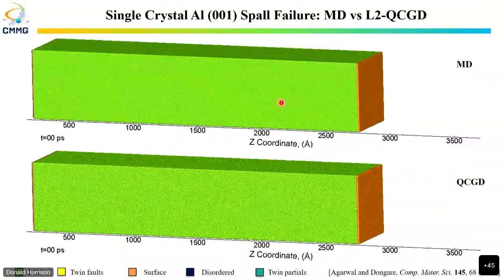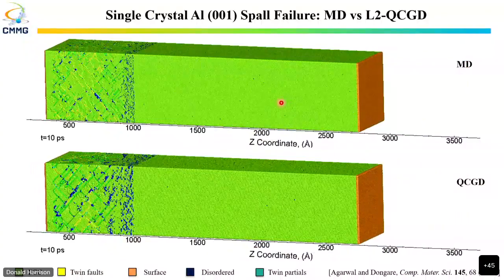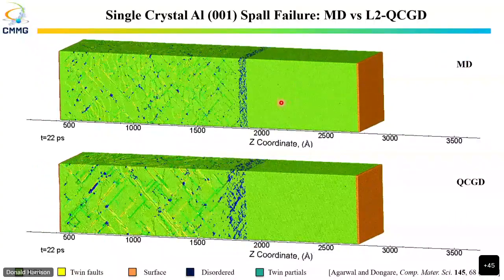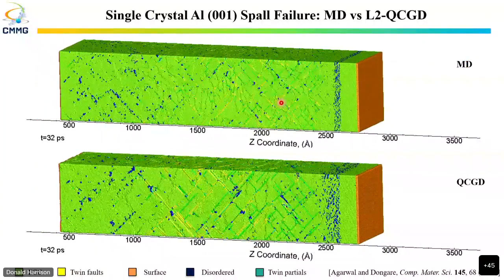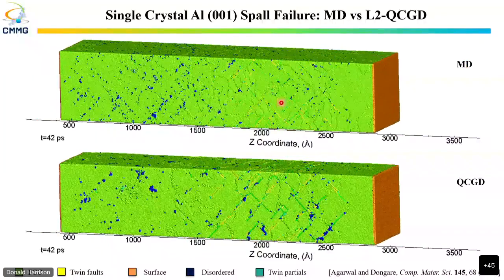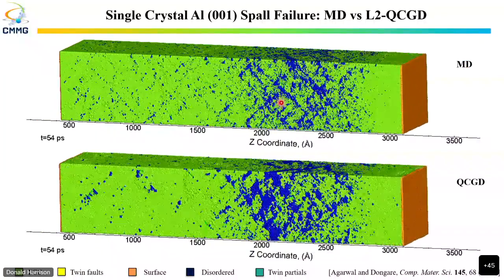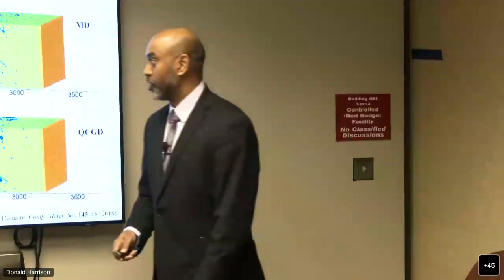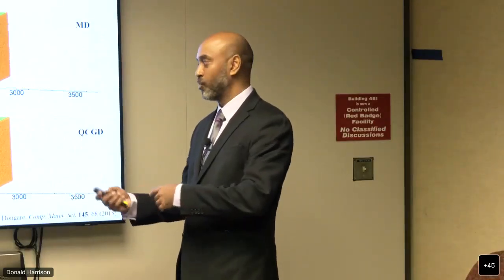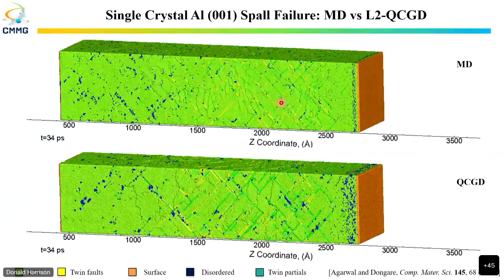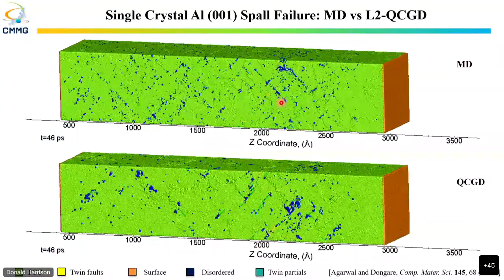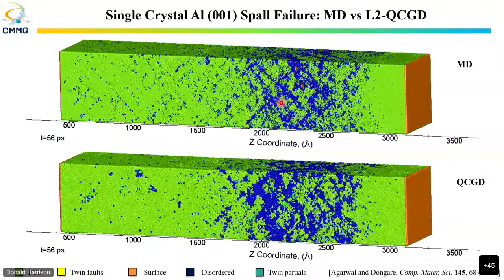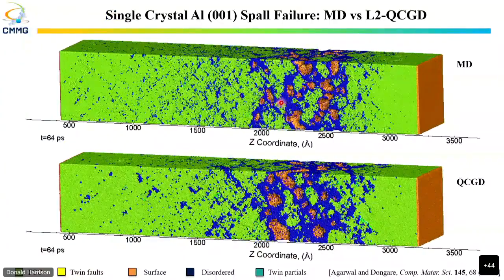You're never going to reproduce exact dynamics, but this gives you the capability to run the simulation at a fraction of the cost, because molecular dynamics is the most computationally expensive system. How much faster is it? Think about it: 1/8 means it's 8 times faster, right? Plus our time steps also increase by a factor of the level of coarsening. So you're looking at almost 16 or 24 times faster. If I want to run an MD simulation that takes 24 days, I can get that done within a day. And I'll show you an example.